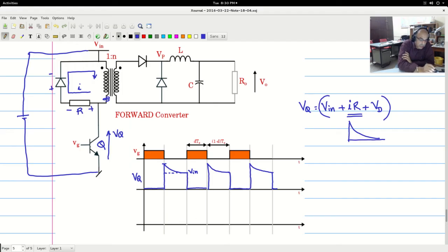So during the time when the transistor was on, this leakage was carrying both the magnetizing plus the load reflected component. So N I naught component. So N I naught plus Im value will be the value which I will start off at this point. And then once the leakage energy has decayed, the magnetizing energy will decay and take this wave shape.